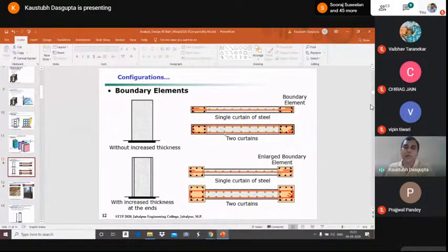So only 22 millimeter is not sufficient for concrete, right? Because when you are going to compact the concrete, you have to place the vibrator needle. It's not possible. Anyone who has seen concreting knows it's not possible. So you need a minimum gap. If you provide 200 millimeter, it will give you another 50 millimeter, so around 72 millimeter is obtained in the intermediate part. Generally, vibrator needle you can have 55-60 millimeter onwards. Different needles are available, so you can accommodate a needle inside.